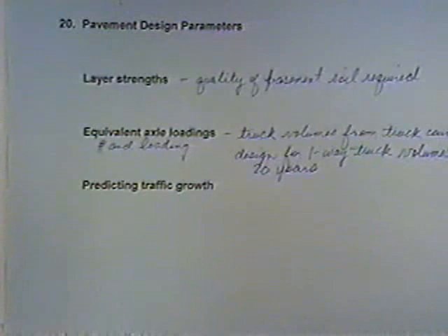We'll also need to be able to predict traffic growth, because typically when we design pavements, we're designing for one-way truck volumes for a 20-year period. So those are the three parameters we're looking for: layer strengths based on the quality of the soil underneath the pavement, the equivalent axle loadings, which is based on the number of trucks, and then traffic growth, where we're looking at a 20-year design period.